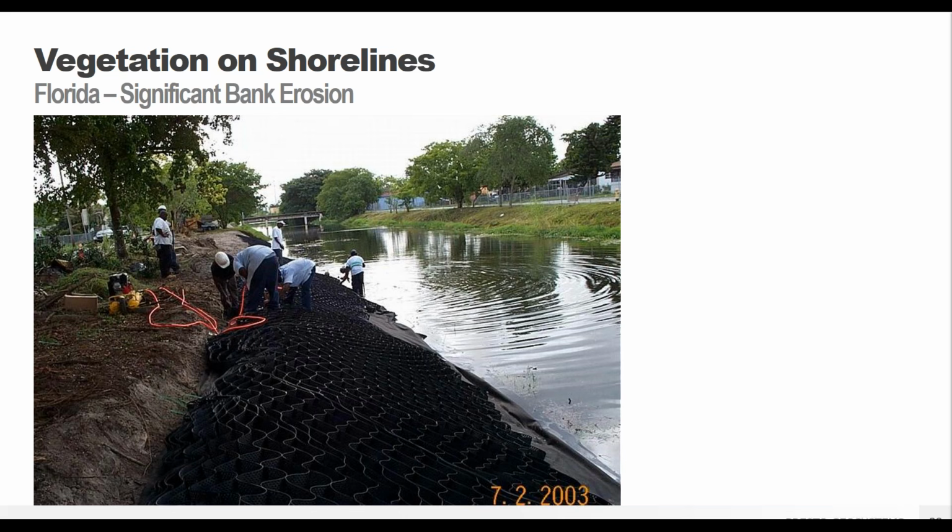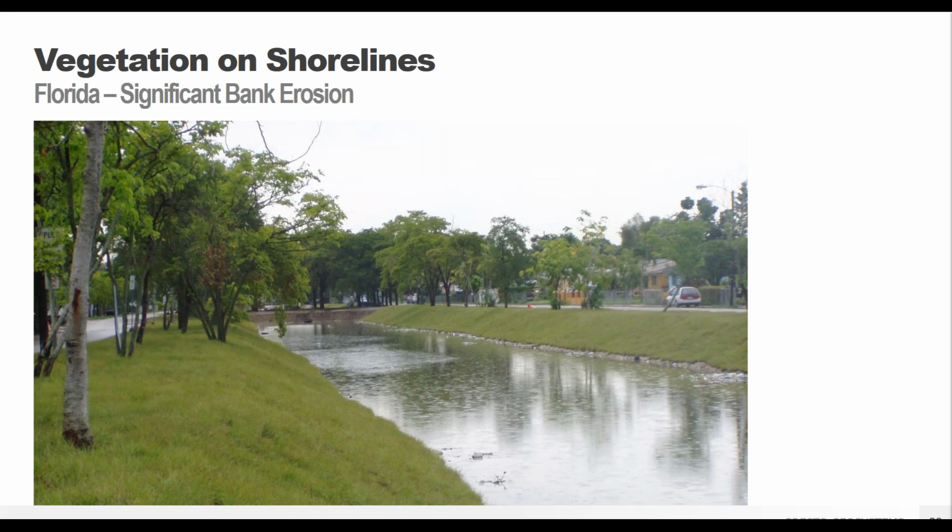Typically, when you know that the area is going to be fully underwater all of the time, you are going to choose either concrete or stone, typically stone, as your infill material, because grass doesn't like to be flooded. And then you can transfer to vegetation in those areas above that typical high water line. So you can see here the final surface after the vegetation's been established.